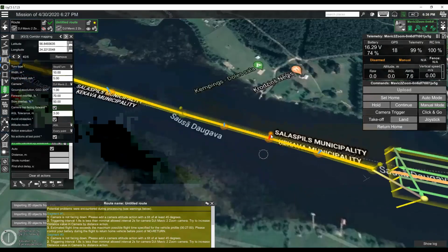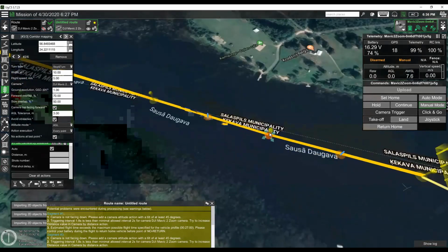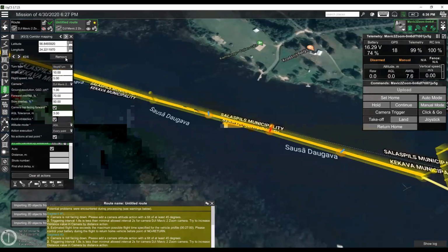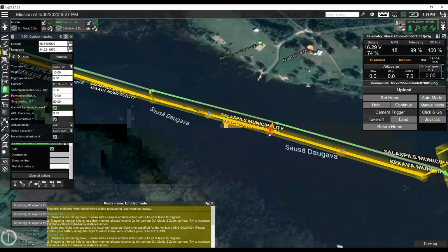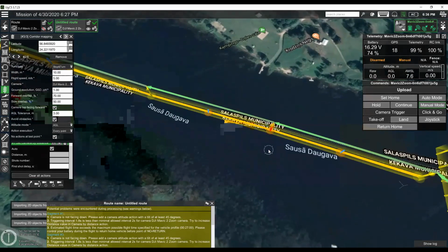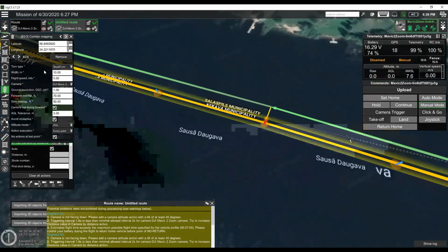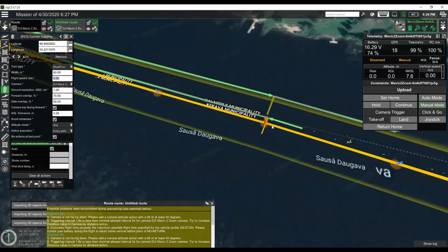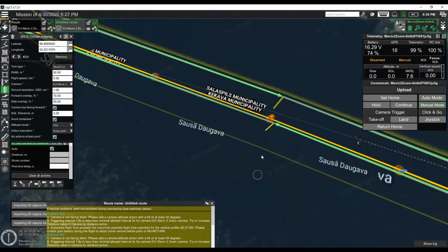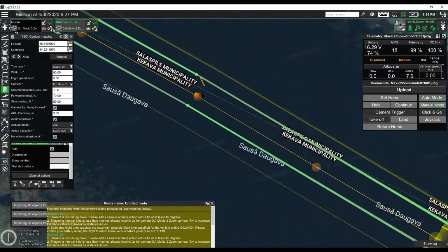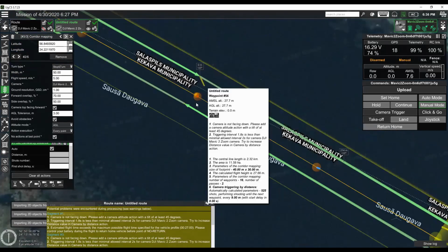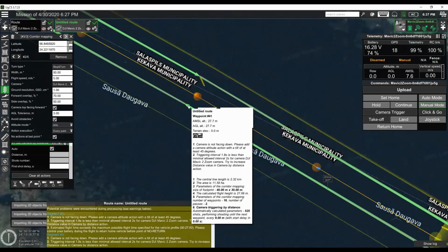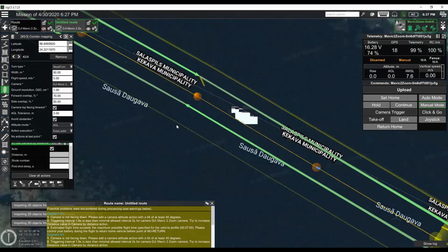You can adjust them by selecting the point or by changing the coordinates. And this actual point will be the waypoint only if you have a single line. If you have more lines, those will be only the coordinates around which the road is created. So if there are two parallel lines, those will be at an equal distance from each side of the point.